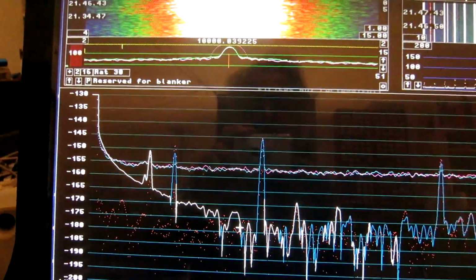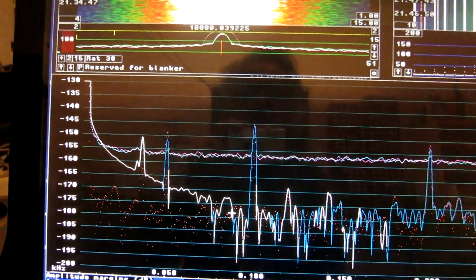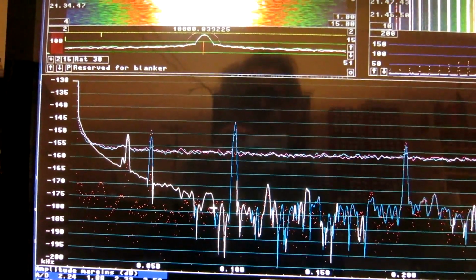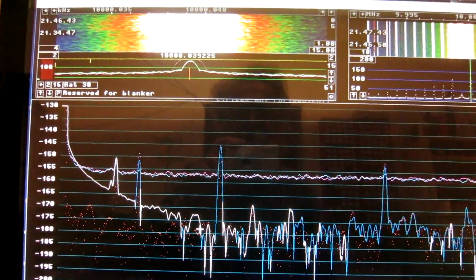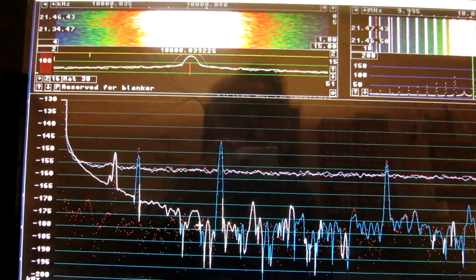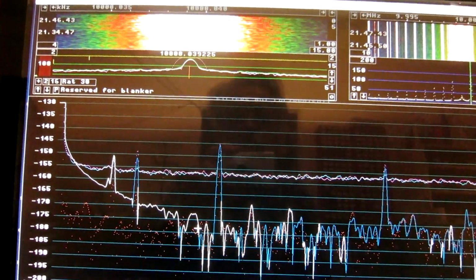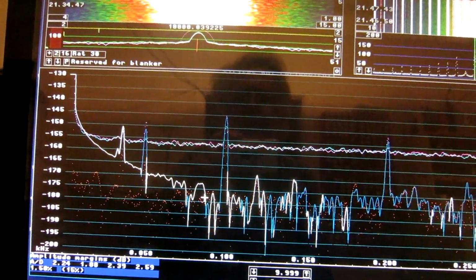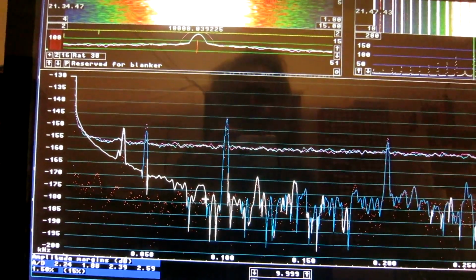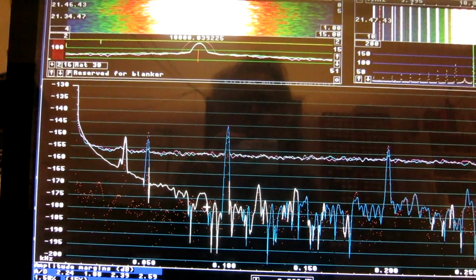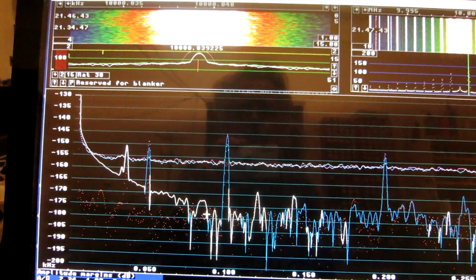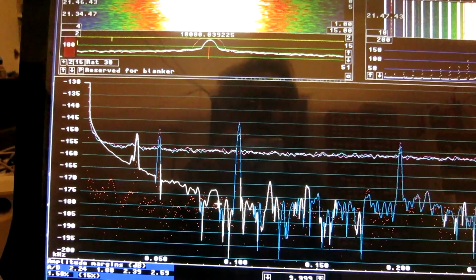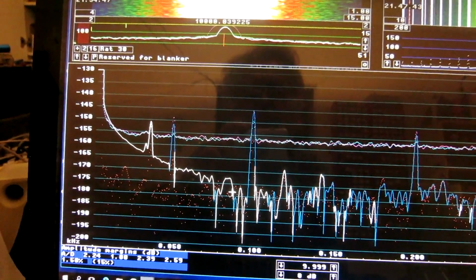I want to bring the amplitude noise down a bit below the phase noise, because when I read about oscillators, it is generally said that the flicker noise of amplifiers contributes to the phase noise of the oscillator. Now, I don't understand that. I thought it would just make AM noise, but I don't know. It is in a feedback loop and things can behave in ways that I don't understand intuitively.